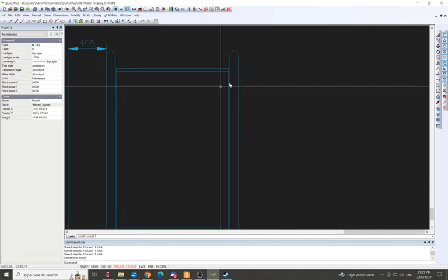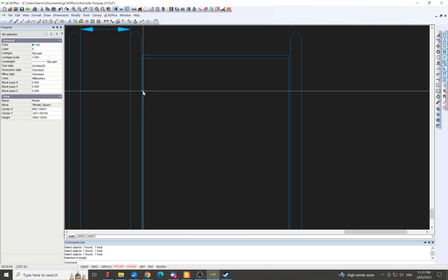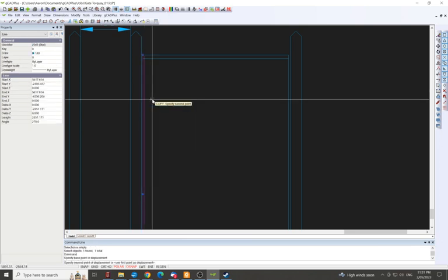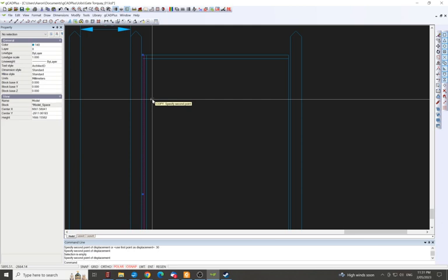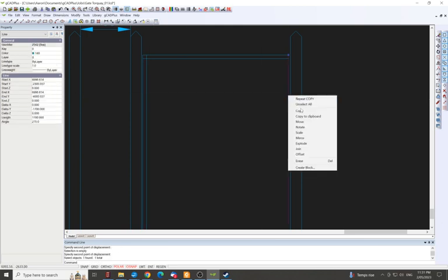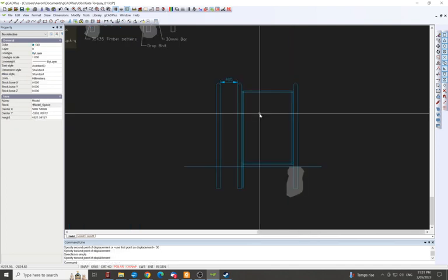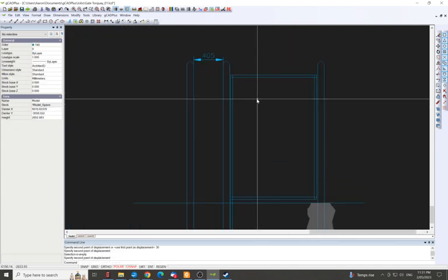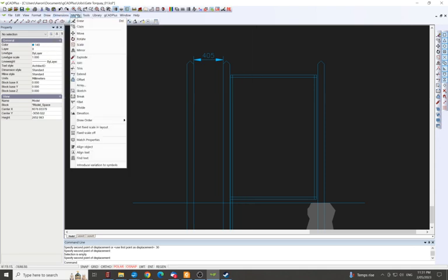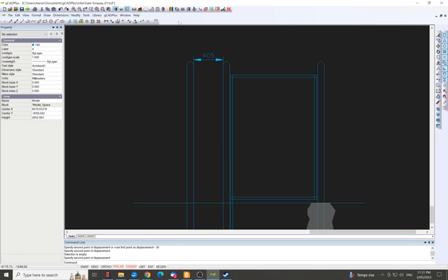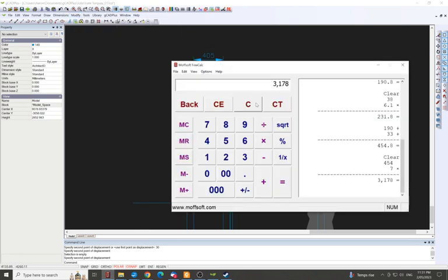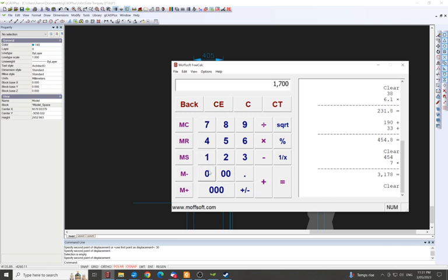So that's our gate. We've got 16mm that side. I'm just going to grab this, copy this. It's going to be 30mm. 30. And if we go to 1700, so when it goes 1700 divided by 2, that's halfway, and then we're going to deduct 15mm off it because the bar's that much.